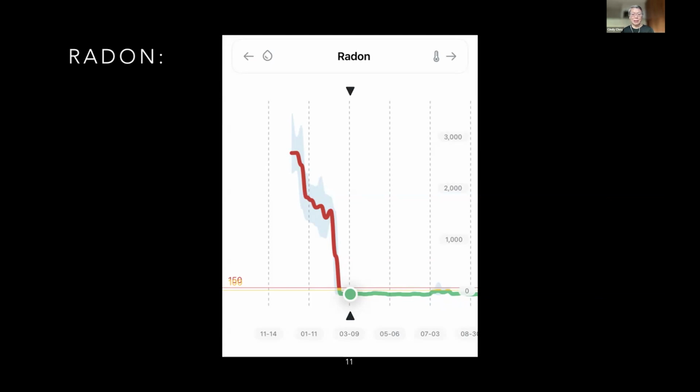So lesson learned here is of all the things you're looking for in a home, one of the things that we should be talking about is just getting an AirThings or some kind of air quality monitor or radon monitor and checking. We are in a hot spot and radon is invisible and it's natural, but it's also something we don't think about, and it has very serious long-term consequences. I feel I breathe easier in this home now.